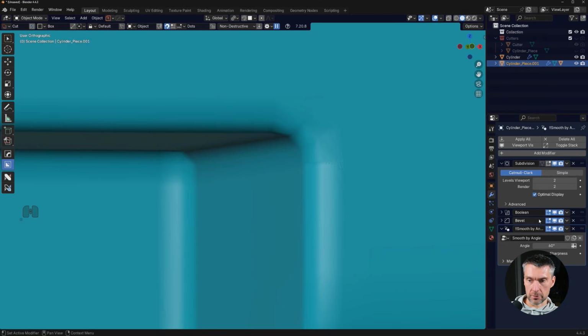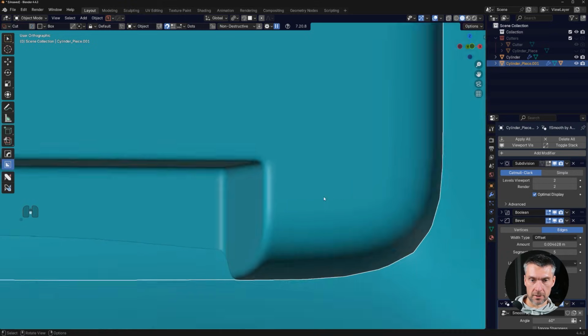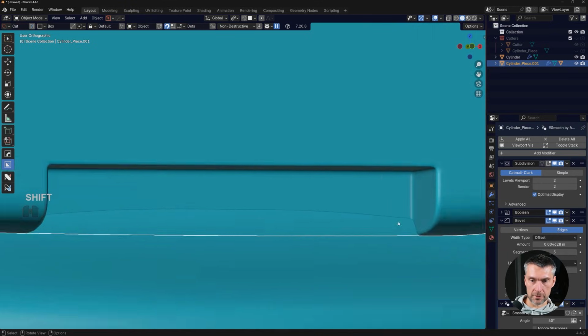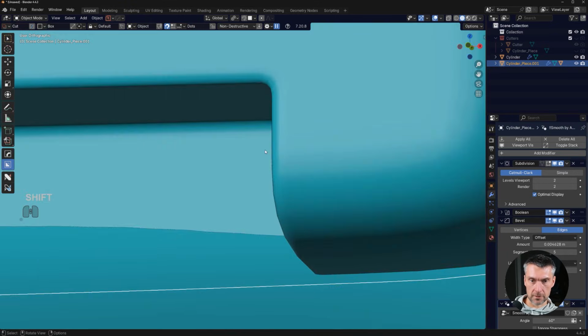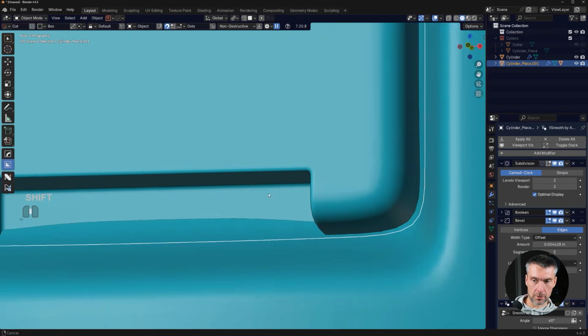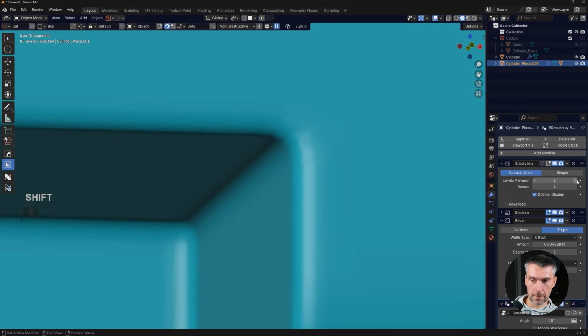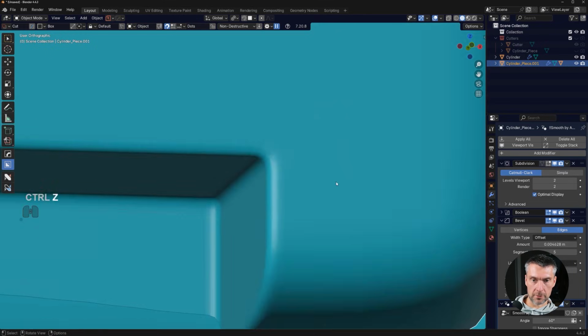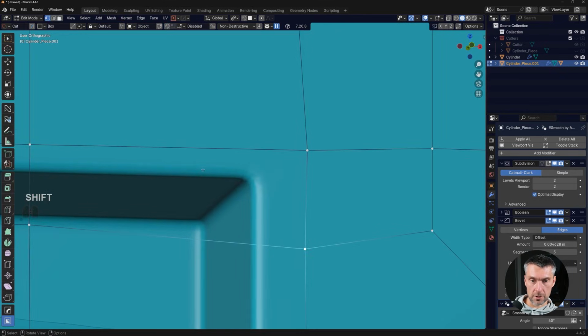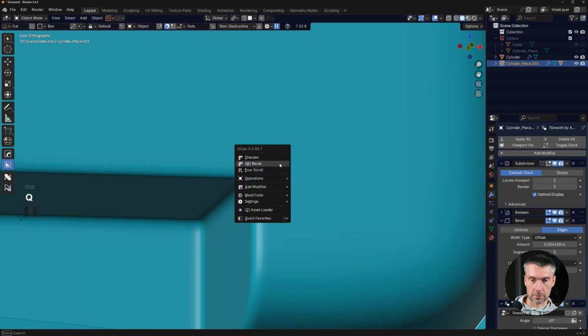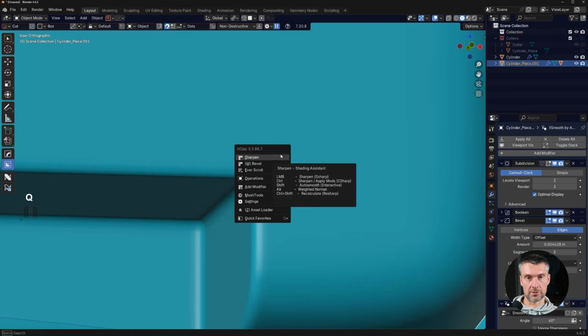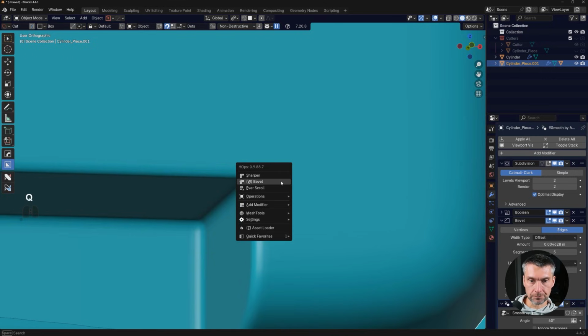Another thing you can do is upgrade the levels of the segments to like 5, and it's going to tighten this corner up a little bit more, okay? And if you bump this subdivision to 3, this is going to be super smooth, right? But just don't overdo it, because remember, you have a bevel running here. So when you overdo it, your subD is going to start collapsing, because watch.